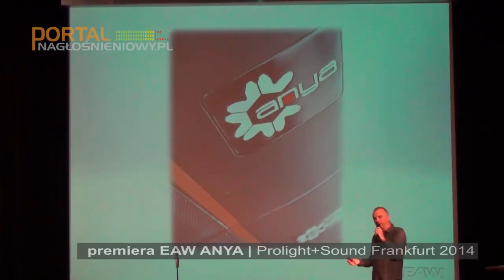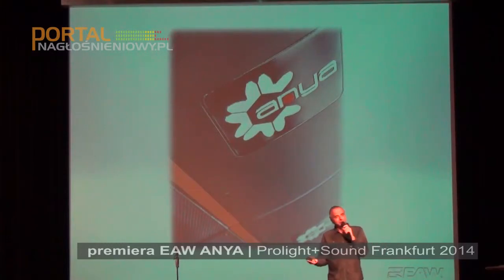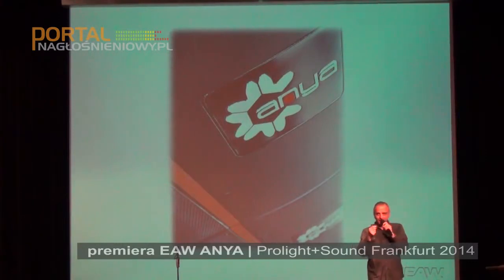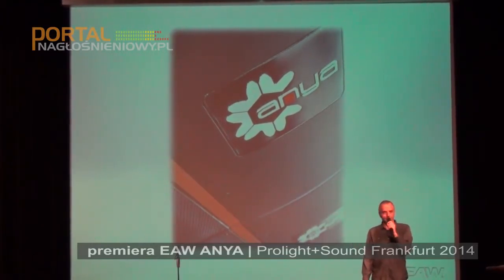But from time to time, sound companies need to test their equipment. They need to know whether the integrity of all the components is good. And this is what we do with Anya. You bring it into your shop, hook the enclosure up to the resolution software, and run a self-test. Each individual device in sequence will emit a sound burst. That sound burst is then heard from the integral mic in the enclosure and compared against the plus or minus reference curve that's stored in the Anya enclosure's memory.